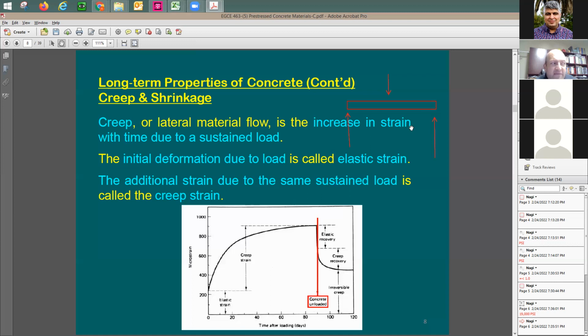All right, so let's say after 1.5 years, I have taken the load out. I removed the load. Would I have any deflection left? You say yes, because the elastic deflection was equal to 0.5 inch. Once you take the load out, it's going to come back. You can recover it. But the inelastic displacement is going to be locked in, which means that you're going to have permanent deflection of 1 inch. You cannot get this back. It's going to stay there in the concrete. And this is what you call here the creep.